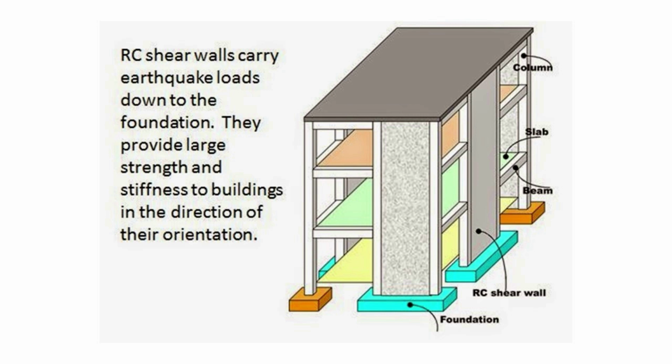Application of the shear wall can go up to 35 stories. However, with the advent of superplasticizers and high-strength concrete, it is now possible to use it for taller buildings in the 50 to 60-story range. Shear wall has restricted openings in walls, thus suitable for residential use. Shear wall structure performs well in earthquakes because ductility is important in the design of shear walls.